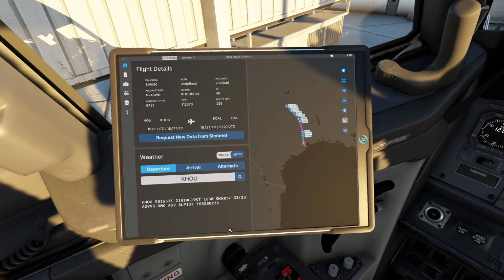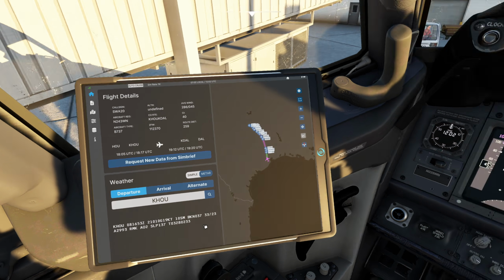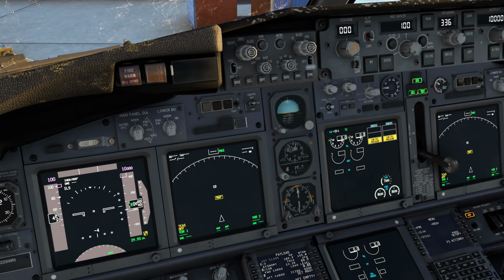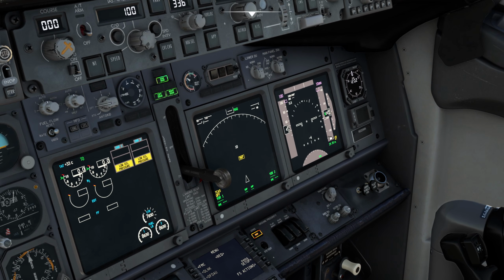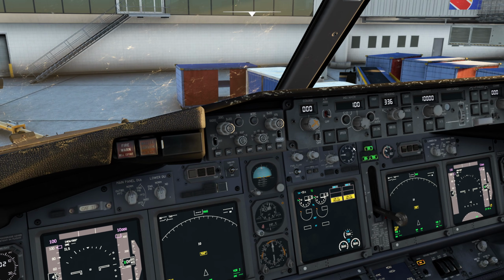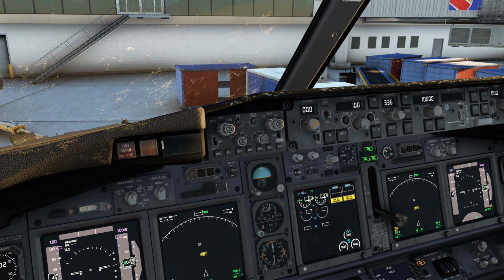Again, we're looking at 2993 on the altimeter, which is only one up from what we have. So 2993 there, 2993 on the standby, and 2993 on the co-pilot display. So altimeter set times three, good to go.